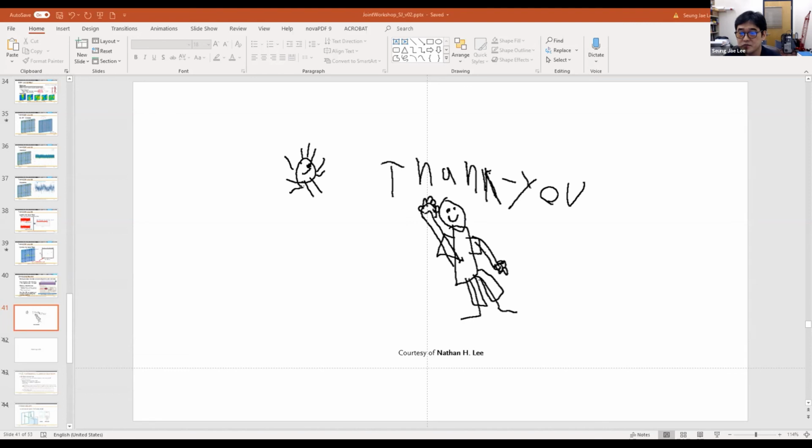So we are still analyzing strain data, because we had some discrepancy when we did similar projects. I think that depends on how you model. Here we use beam elements. On the other hand, the mullion is not really a beam, it has 3D shapes.